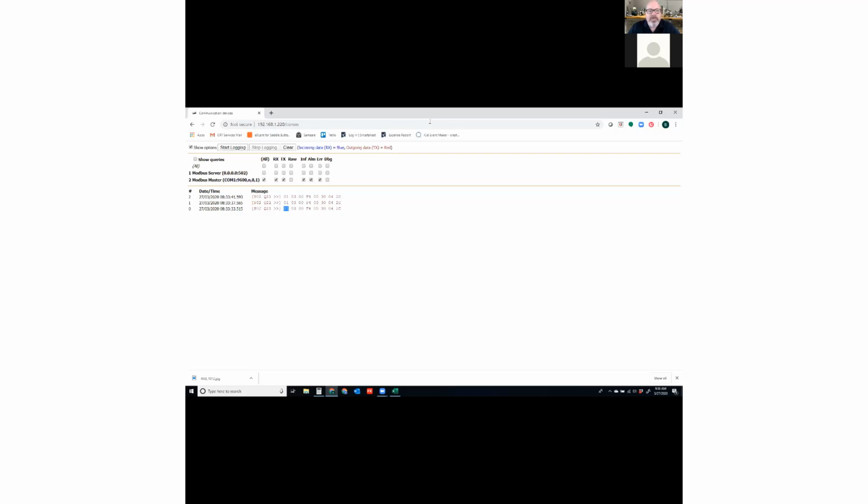Well, let's say for instrumentation, there's HART communications. HART is still a Modbus type protocol, but it rides on an analog signal. You also can use OPC, which is basically more of a tag client protocol. Ethernet IP allows for information to be shared across. So there are a lot of different ways that information can be shared, but in our industry, most typically everything is done Modbus or Foundation Fieldbus.